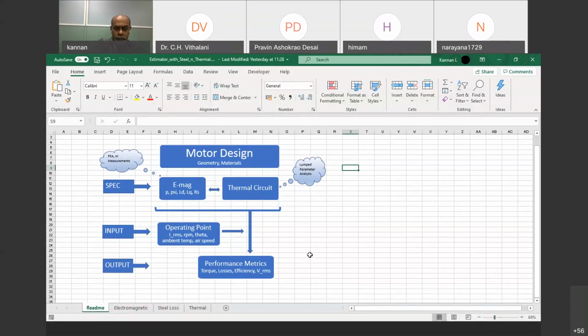You cannot separately go to a market and buy any controller and then connect it with any motor and expect it to run, unless the controller, both hardware and software, is specifically designed and configured for a particular motor. The two will not run together, although each of them may be individually proper products.